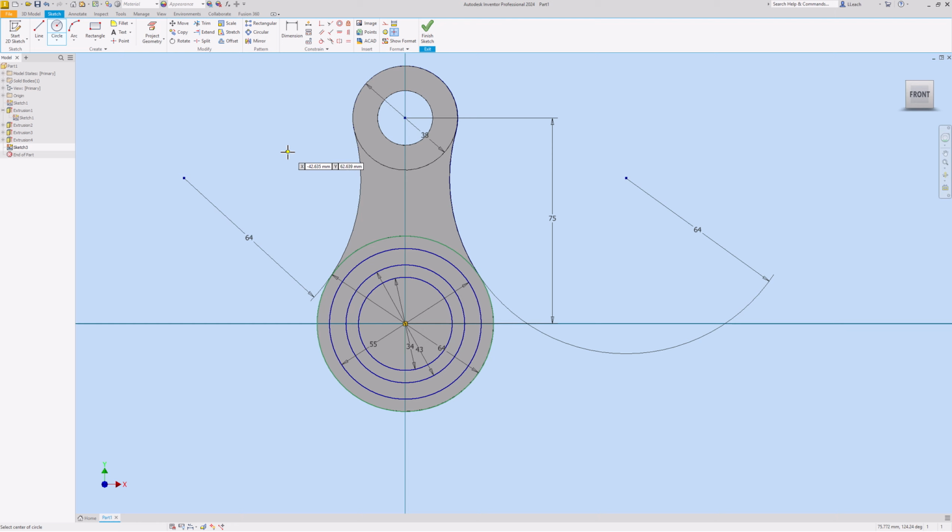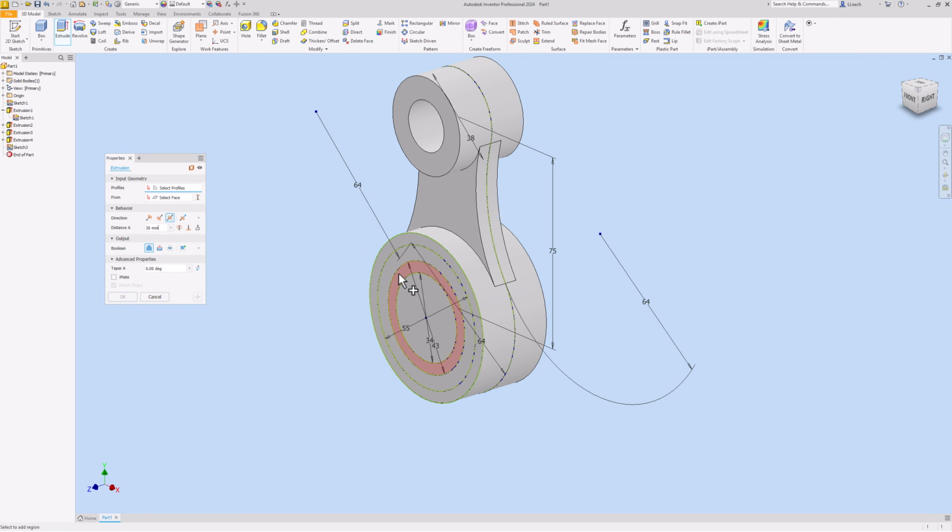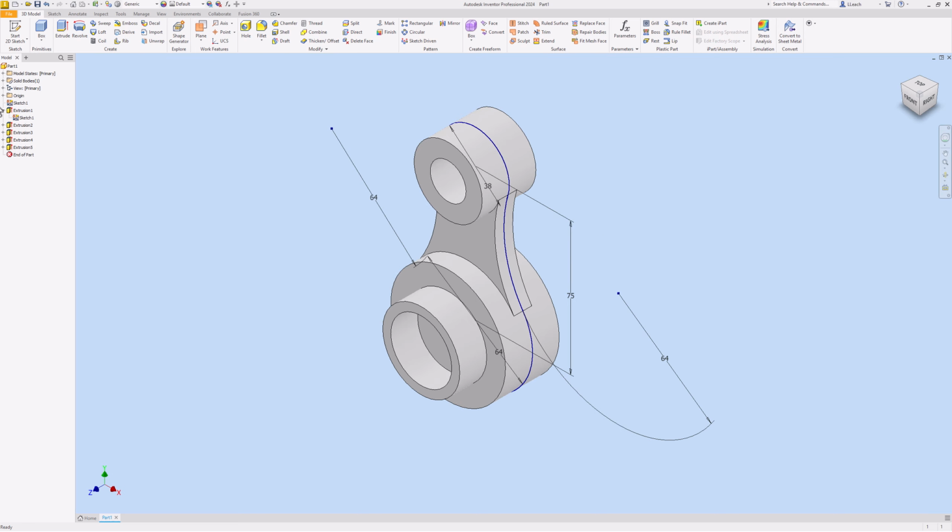So that's just a matter of choosing which way you want to go with this. I am going to finish this sketch. I want to extrude this, not the first one. The second one it gets cut in. So this one here is the one I want, this third one. That one extends out in one direction by an additional 15. So I'm going to type in 15 right here for that. Click OK.